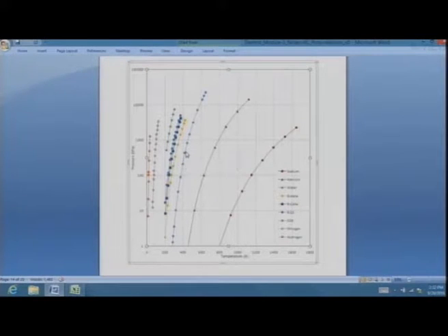Then you have this state here, this line is for water. And to tell you that it's not just water and all these substances which behave like this, we have gone a little bit further ahead, and here these are the properties of mercury. We have seen mercury in the lab, which is a liquid. What it means is that at that 1 bar pressure, mercury has a saturation pressure, there is a vapor pressure at that point, and some mercury vapor would be getting into the atmosphere, but this is very, very small.